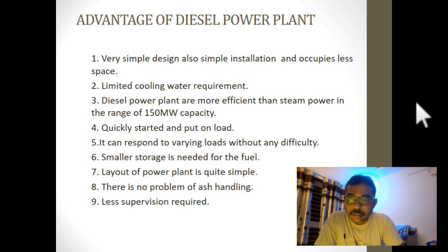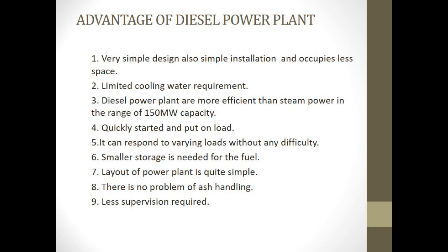These are some of the advantages of the diesel power plant. We can see over here: very simple design, also simple installation, and occupies less space. Limited cooling water requirement. Diesel power plants are more efficient than steam power in the range of 150 megawatt. Quick start and put on load. It can respond to varying loads without any difficulty. Small storage is needed for fuel.